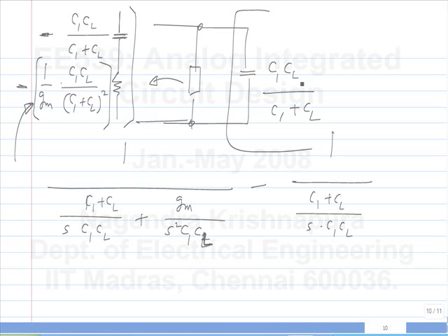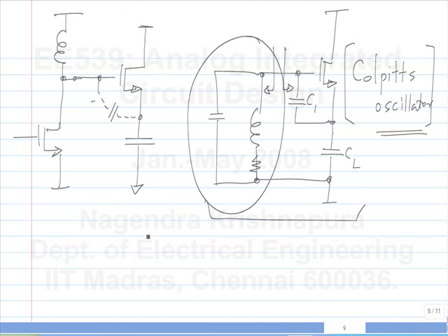If you know the value of C1 and CL properly, you connect this and the circuit will become stable. That is, if it was unstable before, potentially it could have been like this. So now I connect a capacitance and resistance here, it becomes stable because I have cancelled off the negative impedance parts of it. Okay. This again was a pretty common technique with bipolar amplifiers.